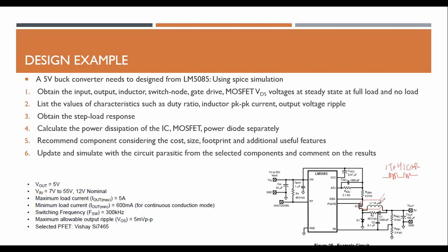But when selecting the inductor, be careful, like in DigiKey, they are asking what is the current, right? So if you're designing this one to drive a maximum load current of 1 amp, at least find an inductor that can carry more than that current, like 3 amp. If you wish to operate at 5 amp, get an inductor with a current rating more than that. So if your output current is 5 amps and if you use a 1 amp inductor, then the inductor will fail and it will be damaged. That's really important when finding the inductor.